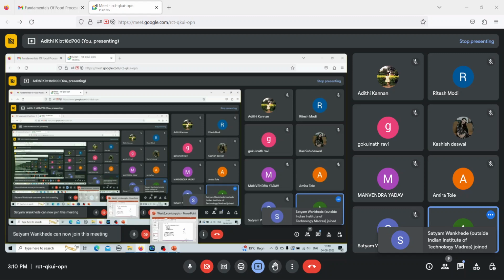So wall effect is undesired because it will add an additional force, and whatever you measure will not be due to the fluid alone, it will be because of the fluid as well as the cylinder wall. So wall effect is undesired in a viscosity measurement. So statement 4 is true. So only 2 and 3 are wrong. The falling ball viscometer experiences 3 forces, and the net force is equal to gravitational force minus drag force minus buoyancy force. So the answer is option A.